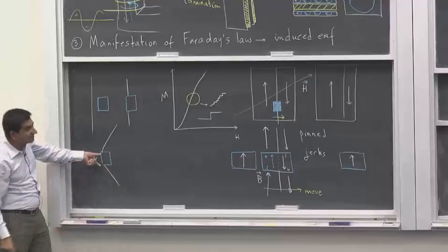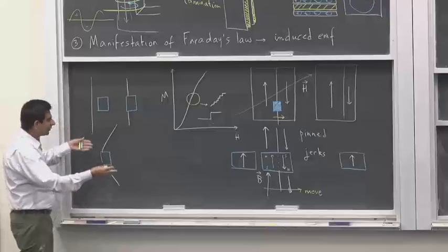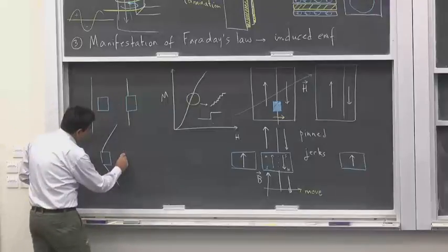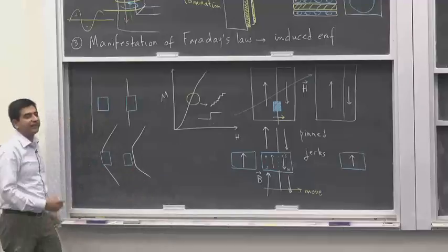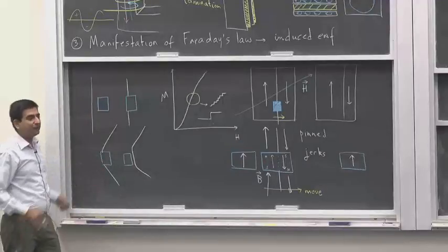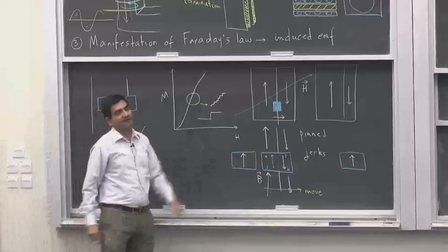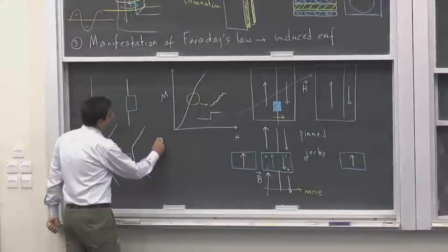So it just remains latched at the position of this impurity. Suddenly, if the external field is so large, this domain wall snaps off. It just moves on. The impurity cannot hold it back. And when it does that, there is a sudden change in the magnetization. And all materials have a property which is called magnetostriction.